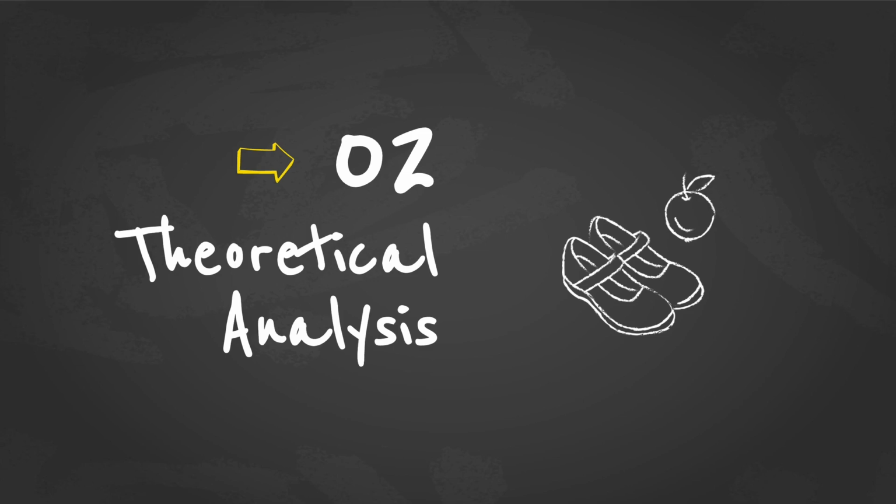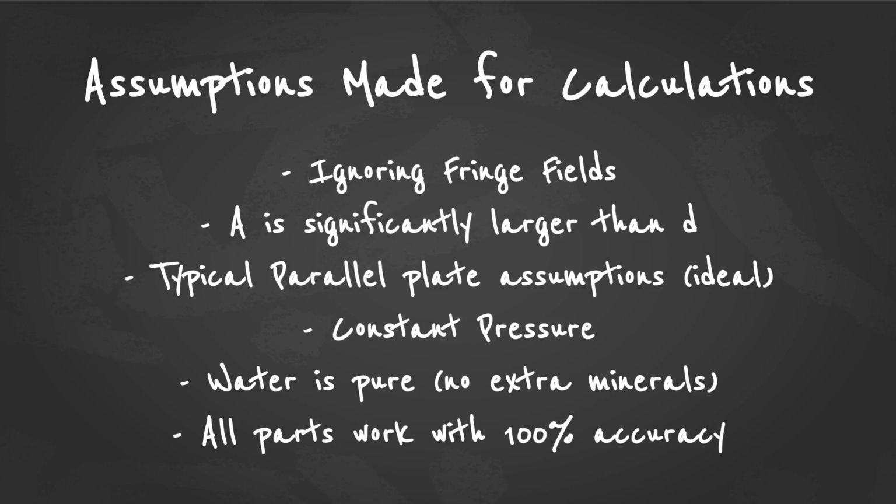Now we're going to begin our theoretical analysis. Before we begin our theoretical analysis calculations, I need to state some of the assumptions made for our calculations. Some of the bigger assumptions that we made were ignoring the fringe fields, A being significantly larger than D, the typical parallel plate assumptions, assuming that they are ideal parallel plates. We're going to assume constant pressure since that has an influence on the dielectric constant.